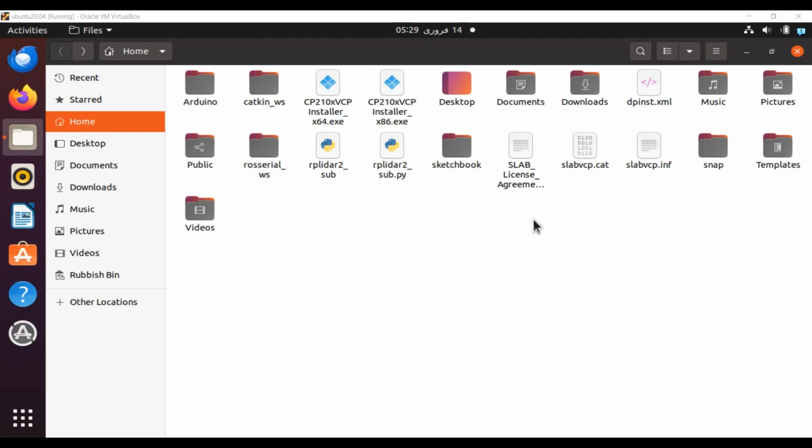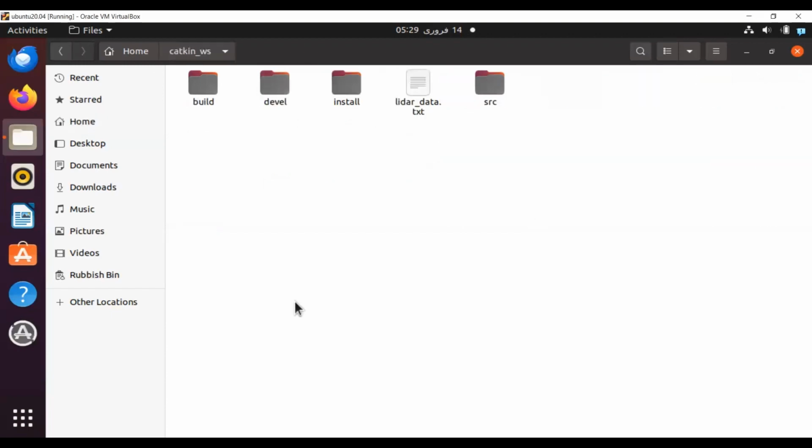We will not go into that side, but we will be limited to the Python nodes and the custom workspace. So this is Ubuntu, and we have set up ROS, the robotic operating system, on this. And I have created the packages. Generally, before you start with packages and nodes, you have to create the Catkin workspace. Inside this Catkin workspace, you have the source folder, install, and devel folders, but the source folder is a very important folder, as in this folder you will have different packages.